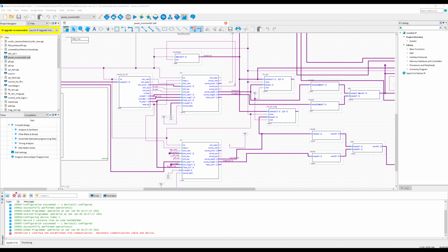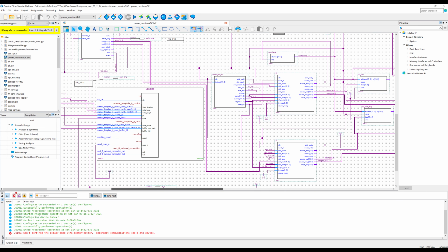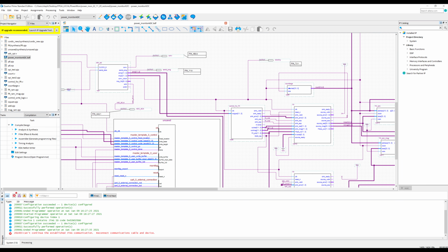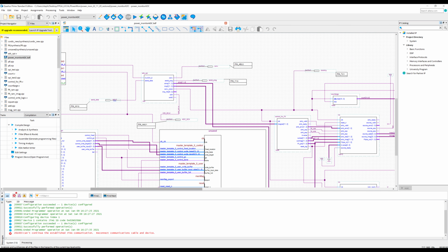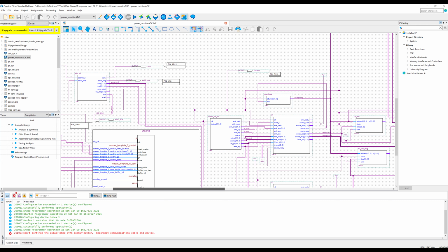So time now to go back to Quartus, and I introduced this in the first video, and we've already addressed the A to D converter code here and the timing requirements and the clock frequencies. So what we have now is a 10.24 kilohertz sampling rate. So the samples are being read into the A to D converter at 10.24 kilohertz. So the FFT sampling rate is 10.24 kilohertz. It's a 2048 point FFT.